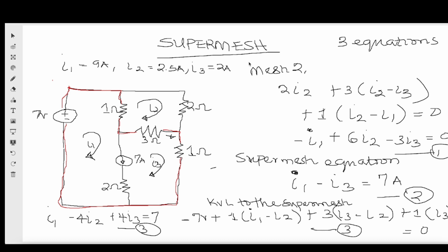One final point I will make mention of in this regard is to keep in mind the location of the source. Current sources which lie on the periphery of a mesh, whether dependent or independent, are easily treated in mesh analysis. Voltage sources connected to the reference terminal are also easily treated in nodal analysis. But when those voltage sources are connected in between non-reference nodes, that's where the problem of supernode occurs, and I've already explained in the last tutorial how you can tackle that using supernode analysis.